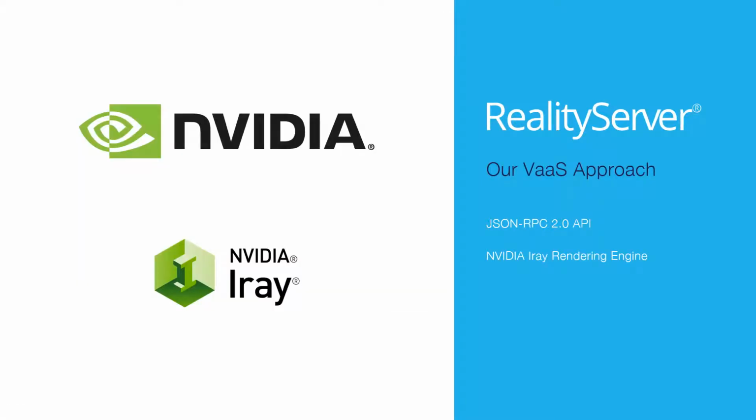For rendering, our initial focus was on high quality imagery, whether pre-generated or live. So we decided to use the iRay rendering engine for this purpose. iRay is physically accurate. It's a bidirectional path tracer and is heavily GPU accelerated. iRay also offers a faster, less accurate mode called iRay Interactive, which in many cases can be used for quicker rendering. It's a progressive renderer, so the results start out with some noise and refine to a completed image. Using the newer AI denoising techniques, you can also speed that up even more.